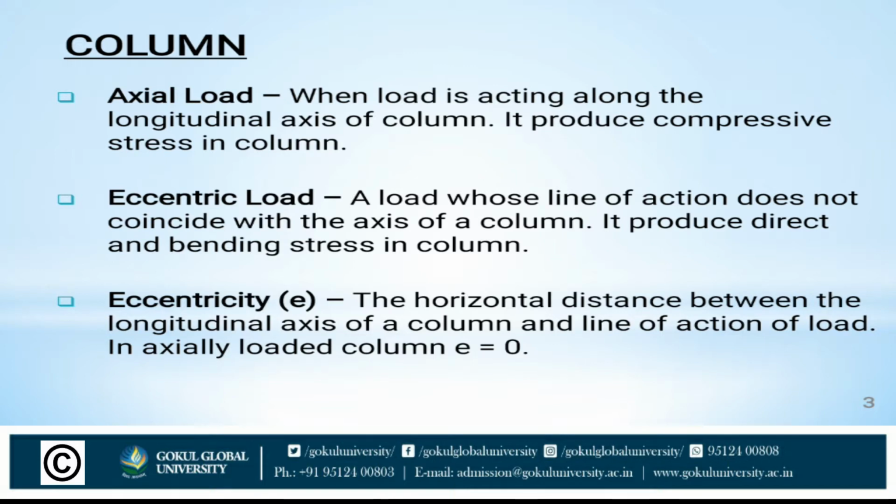What is the column? Axial load: when the load is acting along the longitudinal axis of the column, it produces compressive stress in the column. It's called axial load. Eccentric load: a load whose line of action does not coincide with the axis of the column. It produces direct and bending stress in the column.